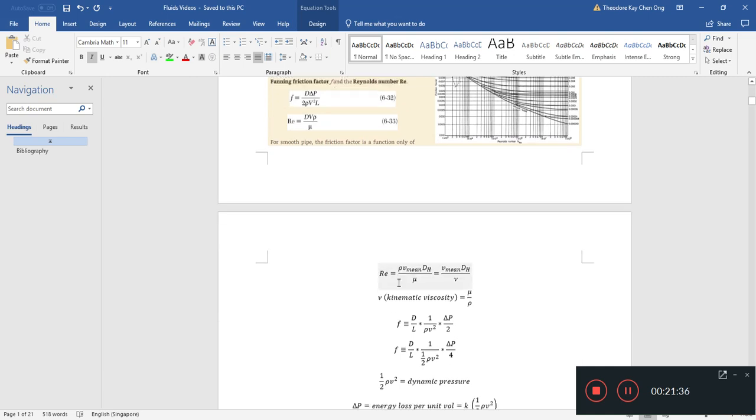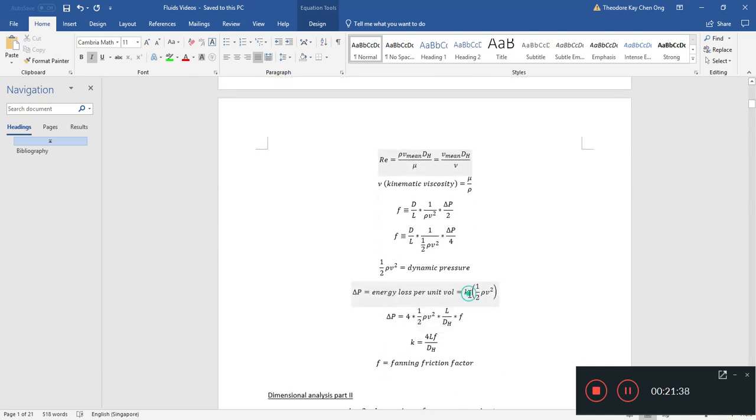We have correlated our k term to this Fanning friction factor by just doing some algebraic manipulation to find how k is related to it, and that will tell us, if our tube is longer, we'll expect more head loss. It's called head loss also, but I haven't introduced it yet. We'll cause more energy loss, and the larger the hydraulic mean diameter, the smaller the k.